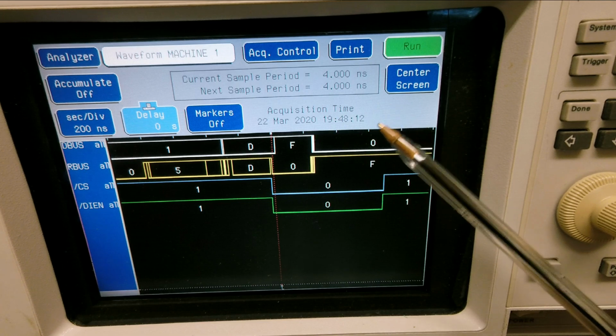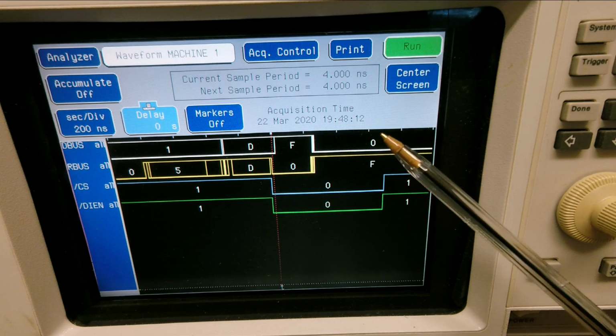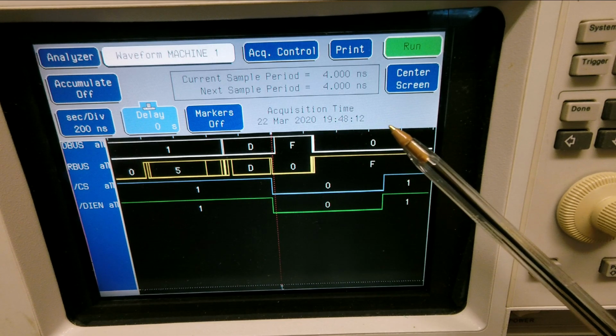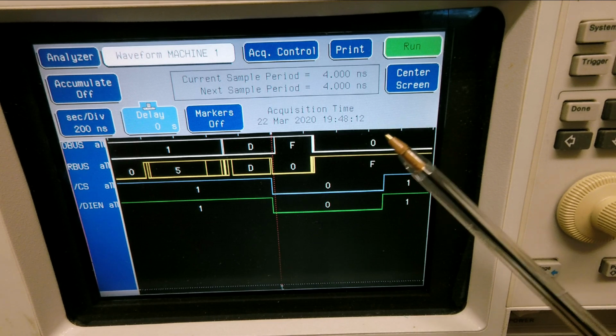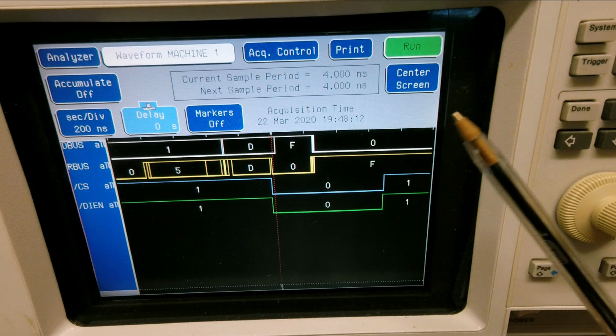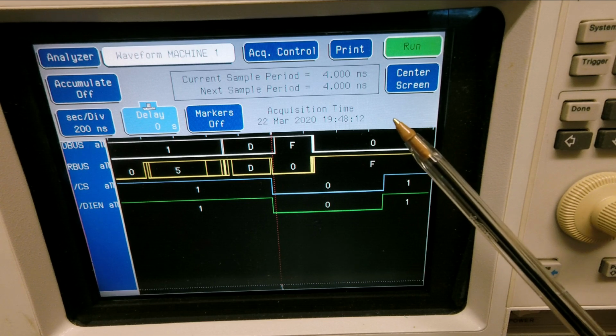But something's still not right, because as we saw on the previous shot, whatever we put into the data bus, it seems to be being squashed. I get a feeling that potentially what's happening is that the buffer is actually shorting the data bus on the bottom 4 bits. It may be something else, but I'm not really sure. I'm going to try changing that chip and see what happens. It's about the only thing I can do at this stage.